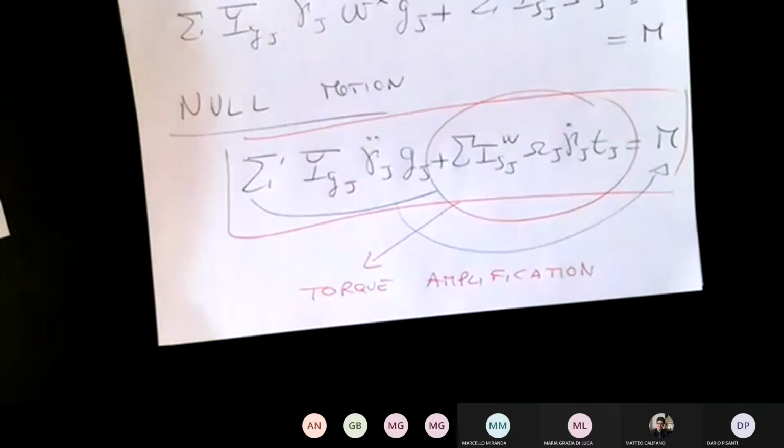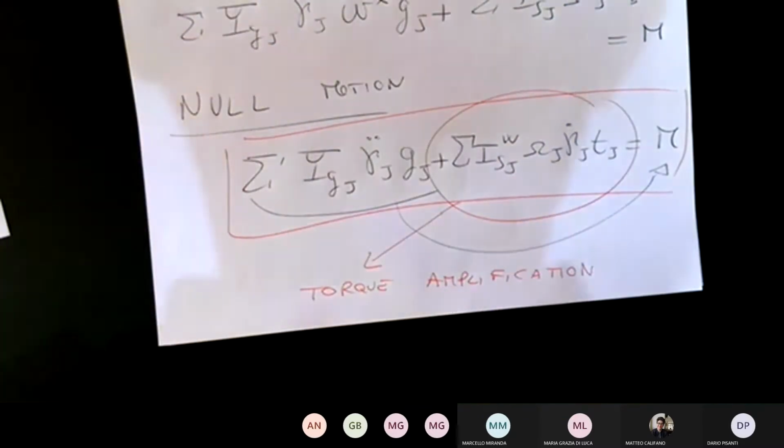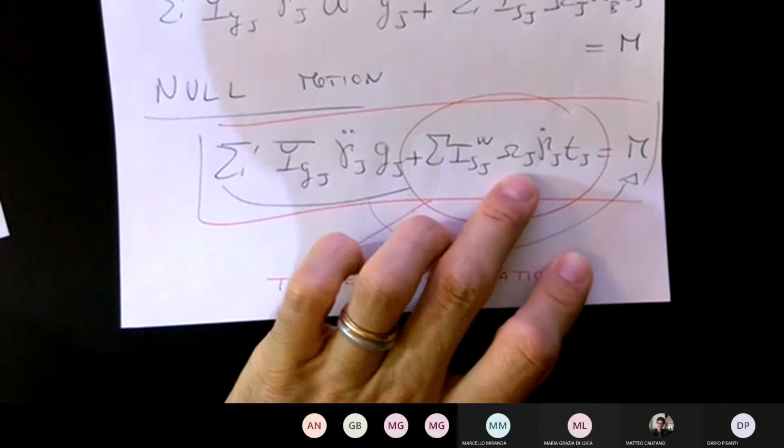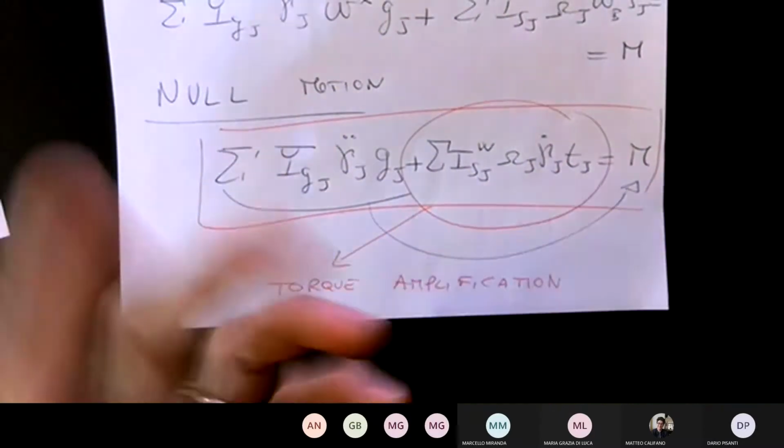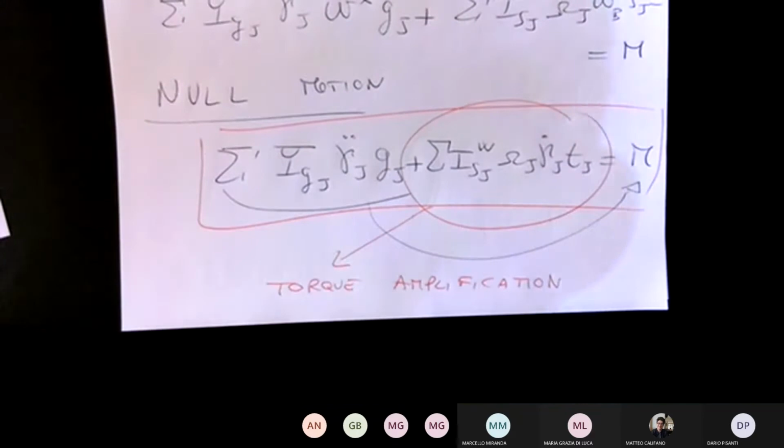So they're usually advantageous from many points of view. The disadvantage is that you have to control them. So you have now to maintain not only the spin rate of the wheel fixed, so you have an actuator right there, you also have the one on the gimbals. So mechanically speaking, they're more complicated to build and drive, of course.